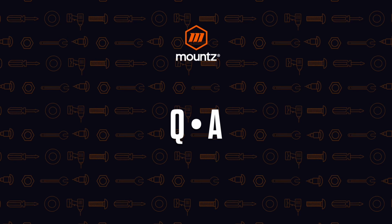All right, thanks, Dave. Next question was, how frequent should a torque audit process event take place for an application? Again, that's going to be determined by your internal processes. If you want to do that once a month, once every 2 weeks, weekly, or daily. Again, it just depends on how accurate you need your process to be. And by doing the auditing, you are validating your process. So there may be vendor requirements, where you may be building a subcomponent for a part, and they may need that type of information. So it's going to be dependent on the internal process and what the actual specification is for you or your customer.